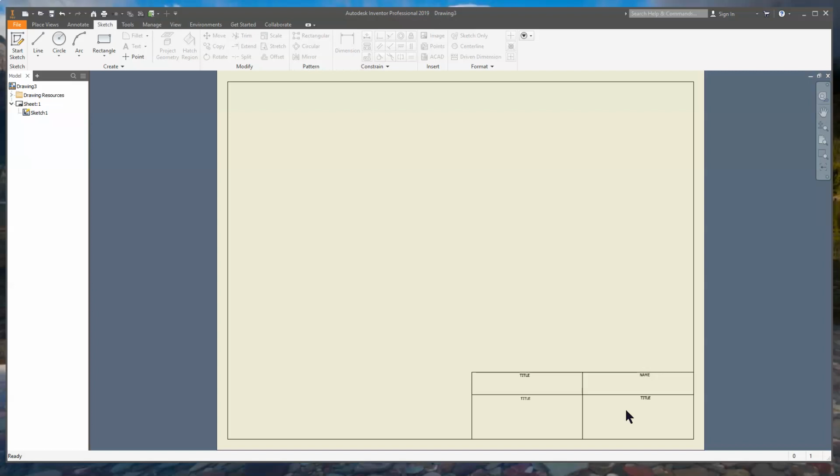I'm going to tell you right now, and on your assignment sheet it'll also say it, you need to make sure that you have certain fields already set inside of your drawings. And so all IDW drawings must be dimensioned on a border to get credit, and the border fields that you're going to need to have are a title, scale, date, quantity, drawn by, tolerance, a revision area, a place for materials, and a drawing number.